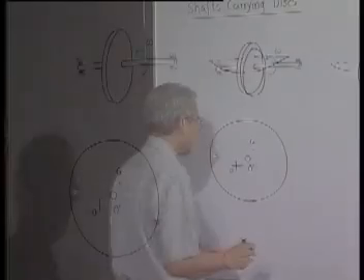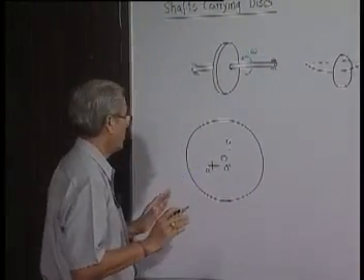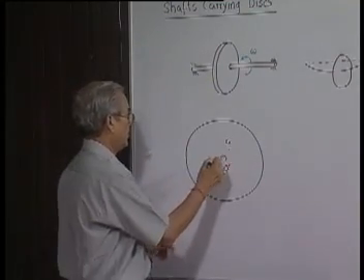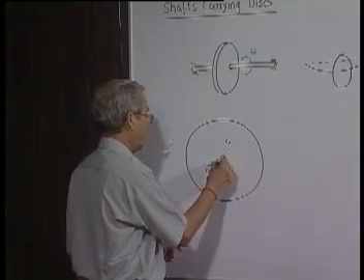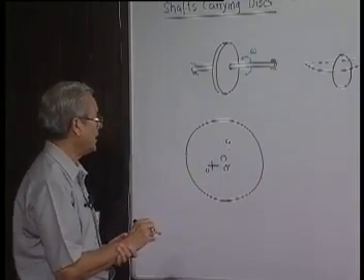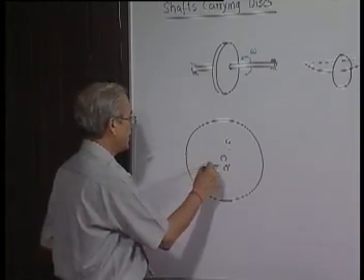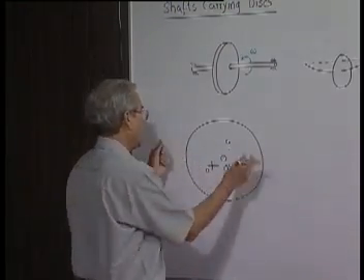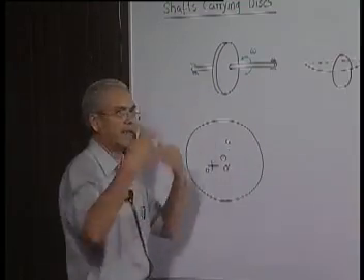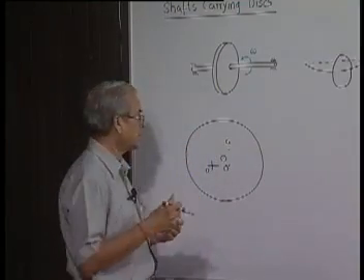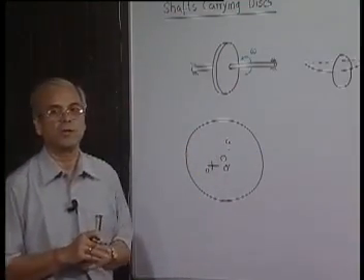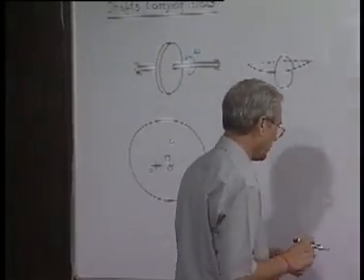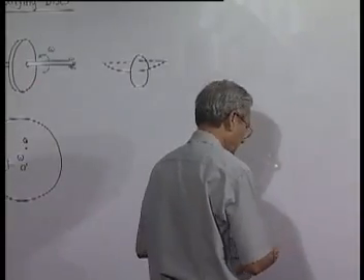We will take up the simplest possible case, where the deflection of the shaft and the location of the G and the center of the disc, that relative position, remains the same. That means the bent shaft and the disc all rotate like a rigid body, and this particular situation is called forward synchronous precession.